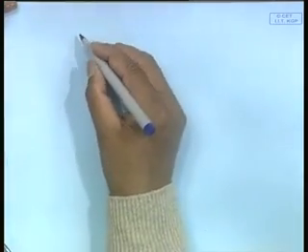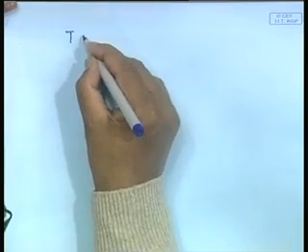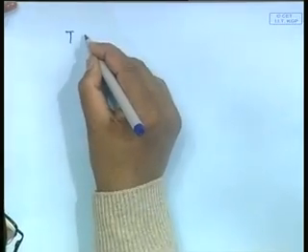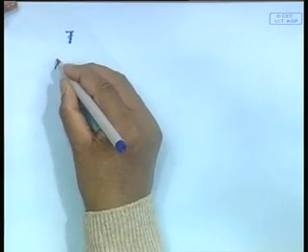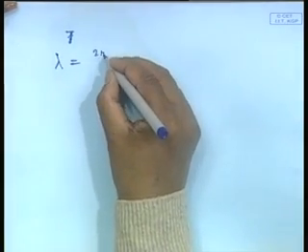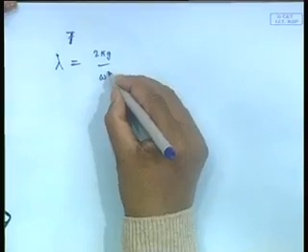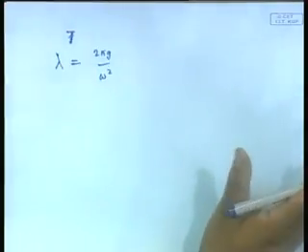Okay. Now, let us look at some of these numbers, therefore, like the relation of this number. Now, typically let us say, let us take a wave period of T. Okay, before that, let me also see this the other way around. Now, lambda turns out to be equal to 2 pi g by omega squared. This is from the dispersion relation, omega squared is equal to gk, straightforward.